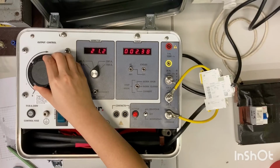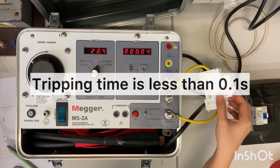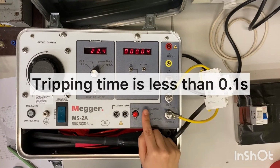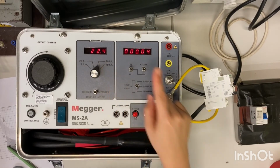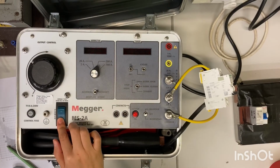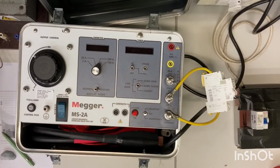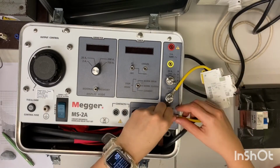This is the last set of data for type B MCB, and you can notice that once I press the button to maintain, the MCB trips very fast, less than 0.1 seconds. So this is the last set of data. You have to record it down, and then we can switch off the mega test set and start the testing for type C MCB.